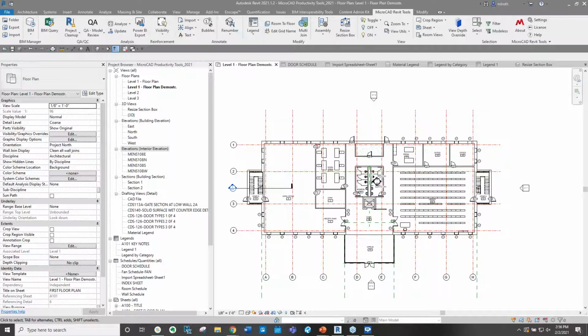So if you're going to be working in a BIM environment, the more RAM you have in your machine, the faster your clock speed on your CPU. Enscape's a little different. We're more what we call GPU or graphics card intensive. So you'll want to make sure that you have a fairly reasonable graphics card installed in your laptop or desktop. We recommend an NVIDIA GeForce